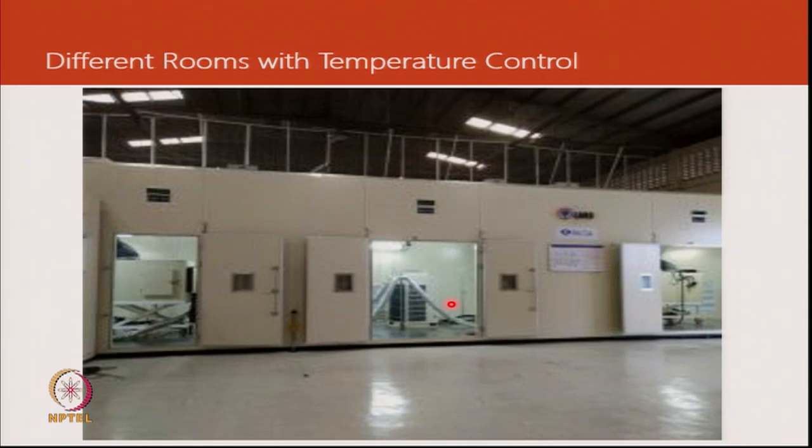The compressor, together with whatever heat it has taken from the cooling side, is going to reject it in the outdoor side. So we can measure the airflow in the outdoor side, the temperature difference across the condenser in the outdoor side, and come to an assessment of what is the heat rejected. The heat rejected has to be a sum of the compressor power and the heat removed from the cold side. So this becomes a way of checking if there is anything missing in the test, if there is some probe that needs to be recalibrated, or it's like a verification. So you check capacity from the indoor side and on the outdoor side and be sure that it is consistent.